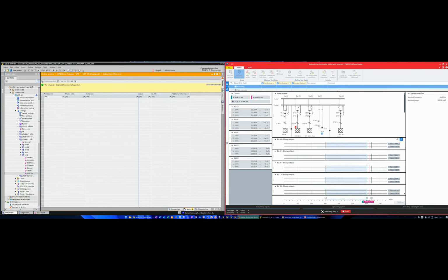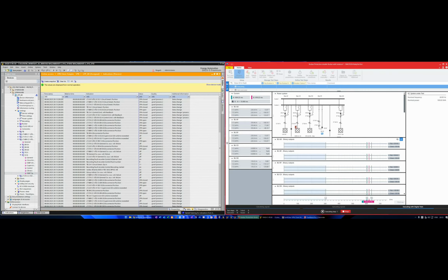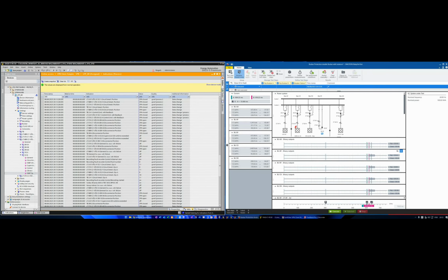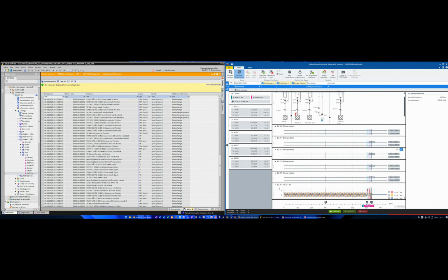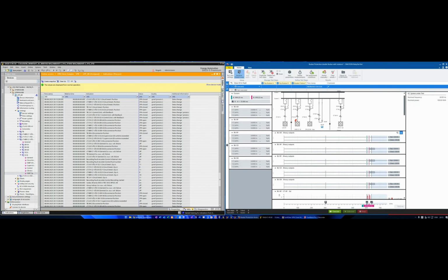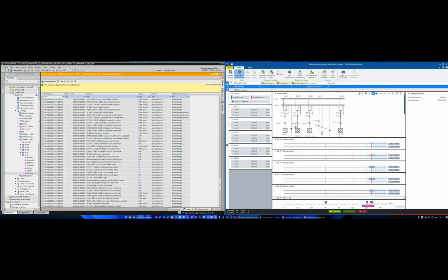So I did the simulation. You can see now we have the first step, we have the second step, and we have these steps applying the fault. And what you have here is this trip in this circuit breaker. We can see that this fault was outside the zone of my bus bar protection, but my bus bar protection operated incorrectly, because I told you about the interval time that we have for the current that will flow in this fault and the status of the circuit breaker.